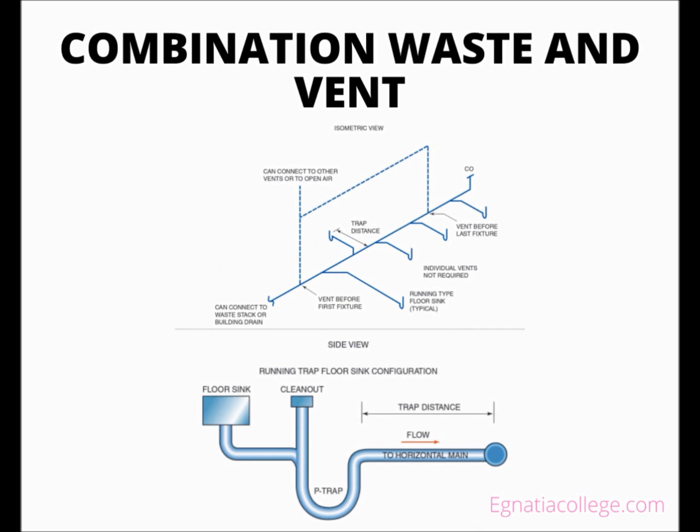This design is most common in large commercial kitchens and manufacturing plants where there are not enough available walls to install numerous vents. The size and type of fixtures that can be connected to this kind of system are strictly regulated and listed in a code book. Slope is required and dictated by codes because this system is in the horizontal position and often cannot slope more than 1/4 inch per foot, regardless of the pipe size.